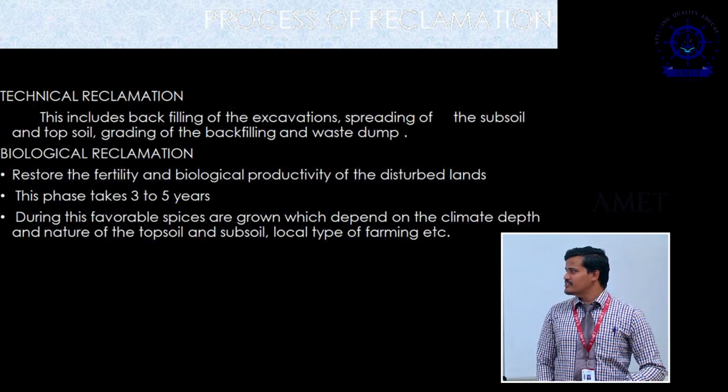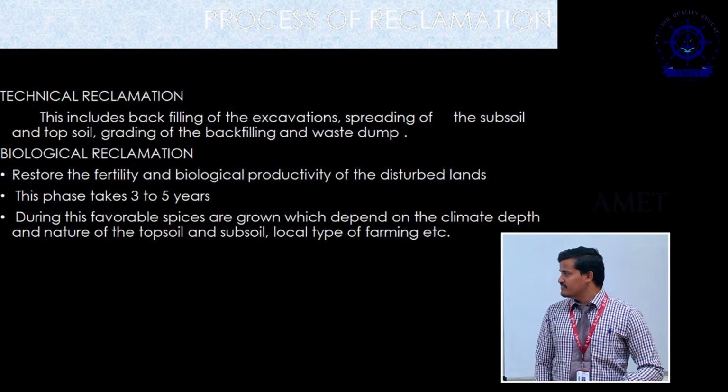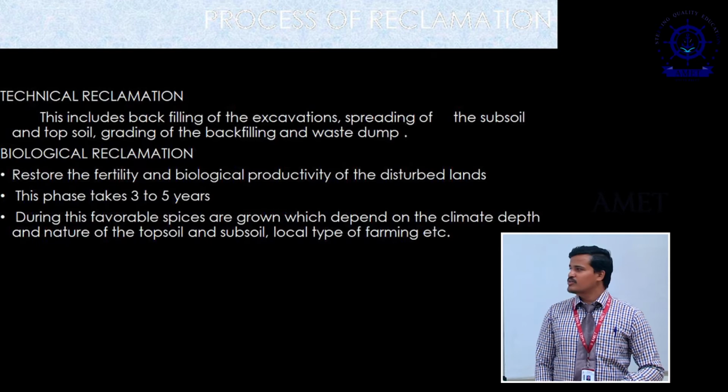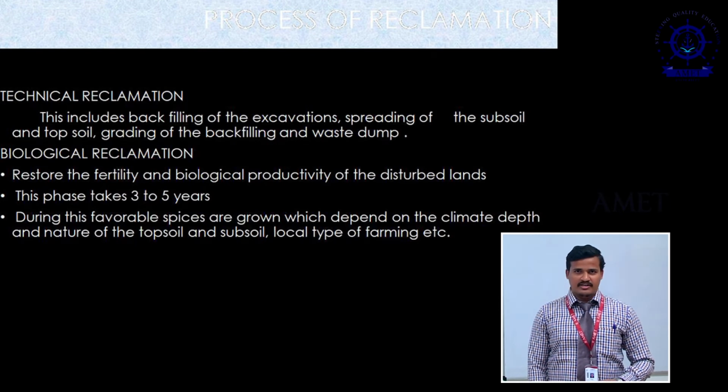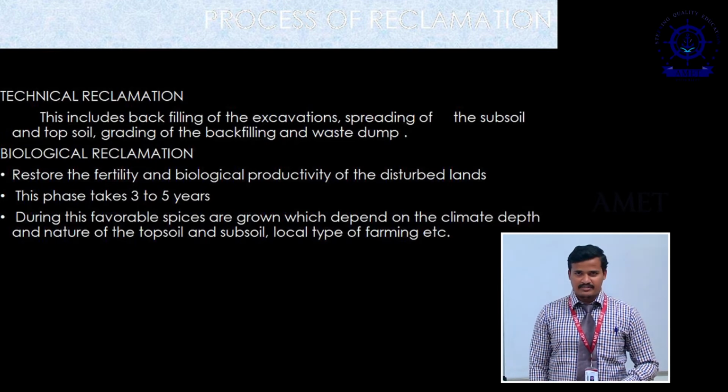Technical reclamation includes backfilling of excavation, spreading of the subsoil and topsoil, and grading of backfilling and waste dump. This technical reclamation can be done with the help of just a dozer, a dump truck and a shovel. This process can be done in maybe 2 or 3 months, based on the size of the mine.